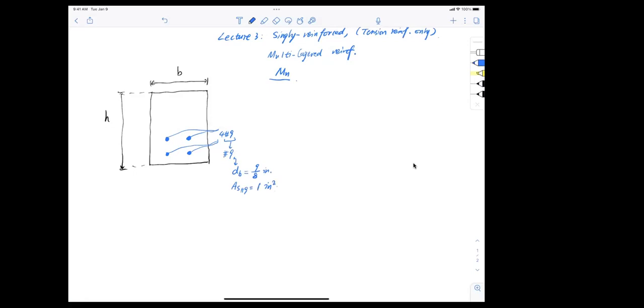Now I have all the dimensions at my disposal. And to sweeten the deal, I tell you that I have a concrete cover for the bottom reinforcement of 2.5 inch, using 2.5 inch plus the chairs. Then I put a spacer between the top layer and the bottom layer at 2 inch of distance. This sets me up with 4.5 inch of cover for the top layer.